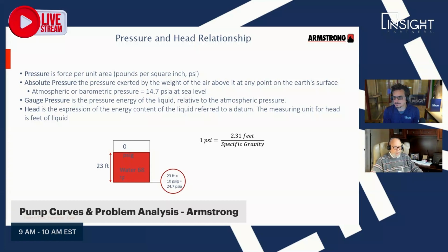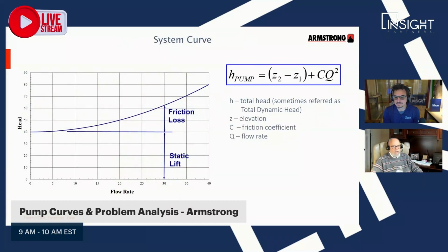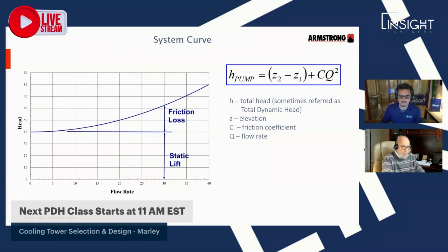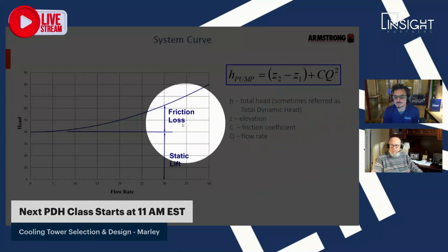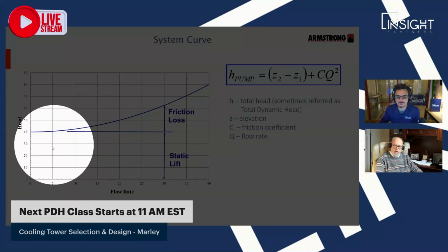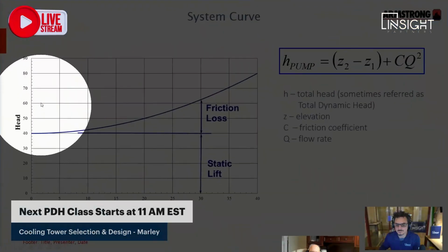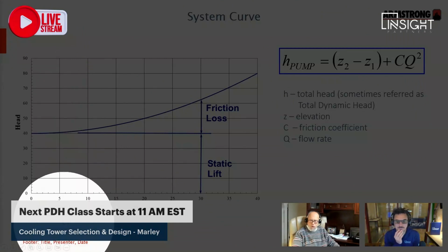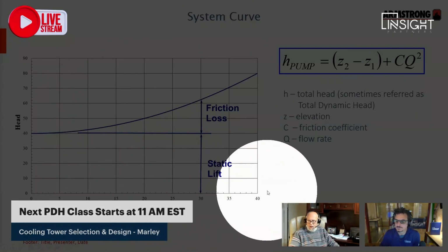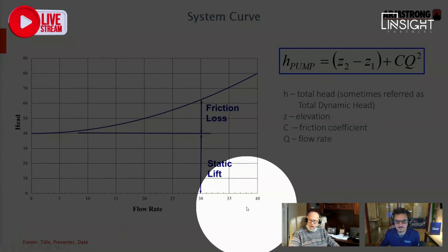Yeah, me too. So one of the basic component parts of a pump curve is understanding the different numbers that are on the curve. If I look at the left hand side of the curve over here, that is my head losses. That's my system head. And across the bottom is flow rate. This particular one is in gallons per minute.